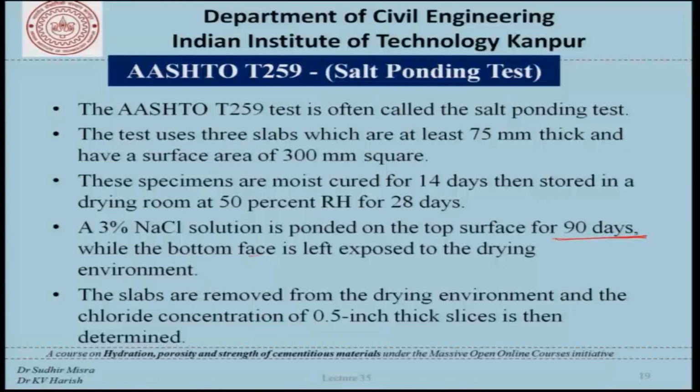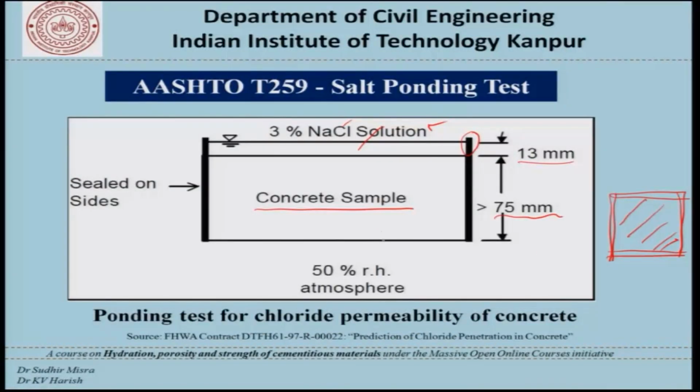So, this condition here of the bottom face being left open is to basically allow the water to permeate through if it comes to that. The results obviously will be very different if we were to seal the bottom as well. So, these are the kind of things which, as a student of civil engineering or a student of concrete engineering,